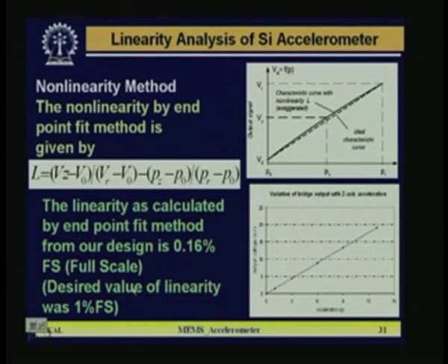In that way, as far as linearity is concerned, we are satisfying our specification. Off axis we are satisfying our specification, and in the modal frequency analysis we are satisfying the natural frequency. So, those three things have been done in our simulation, and let me stop now.